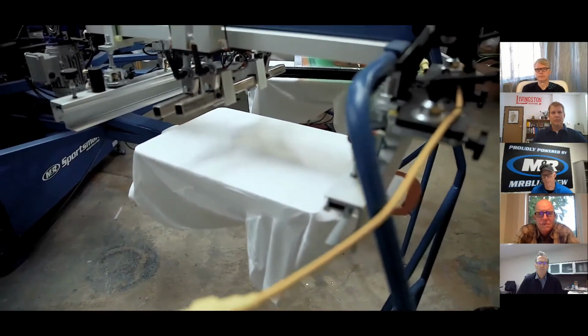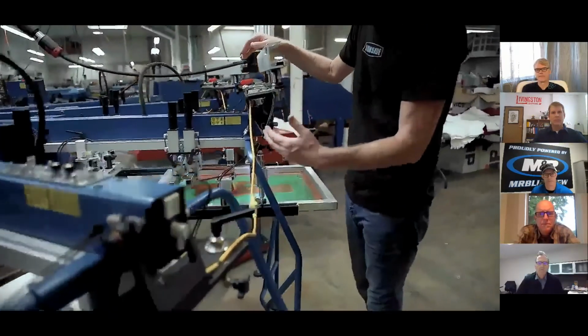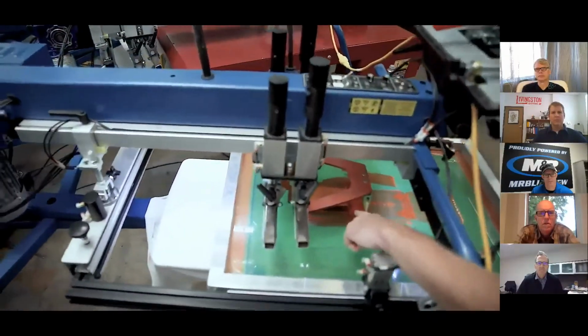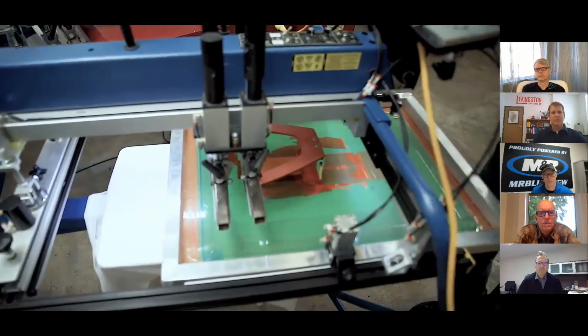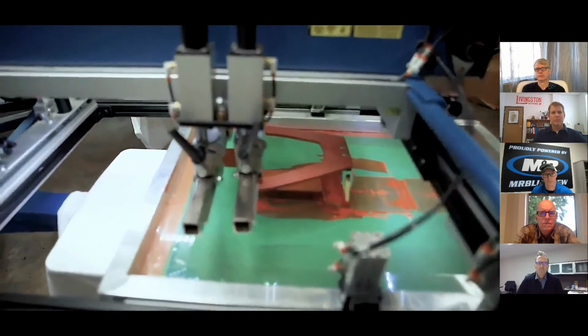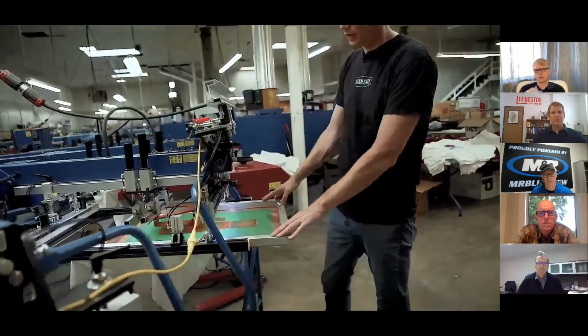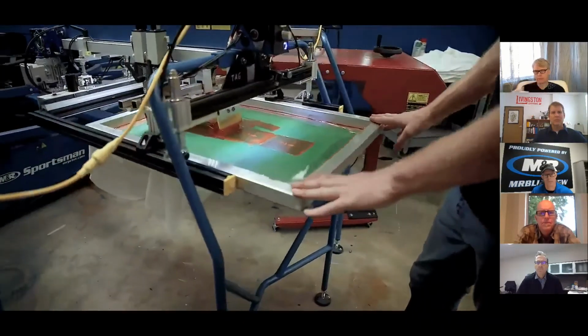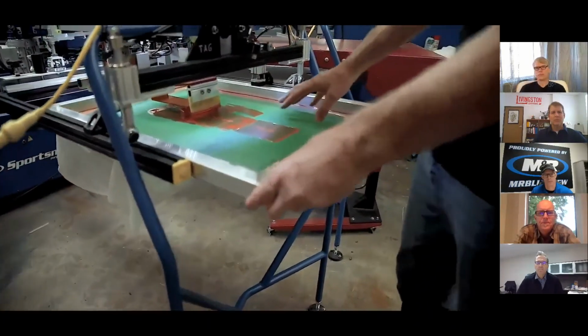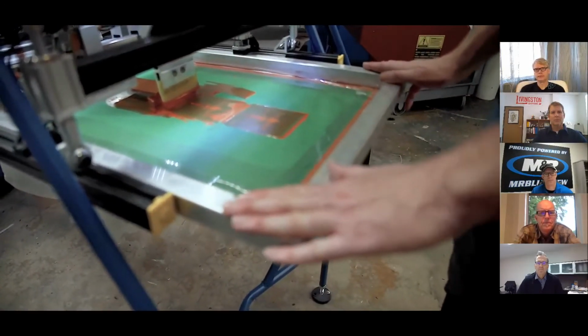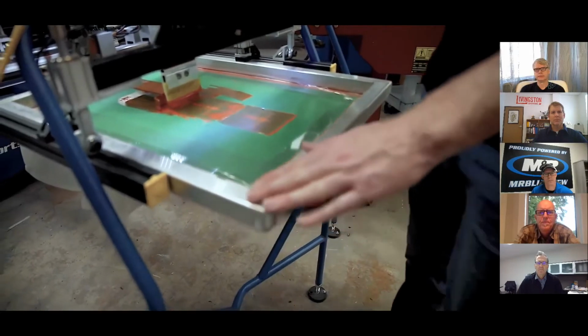So back to the screen holder, the way we're able to print outside the normal print area is we're using this extended squeegee and flood bar, and it snaps on just like a normal squeegee and flood bar work. We also have a very simple system in order to line up the screens. So typically we will burn 3 sizes on one screen, and again, this is just a standard screen, so you don't need any special screens anymore.